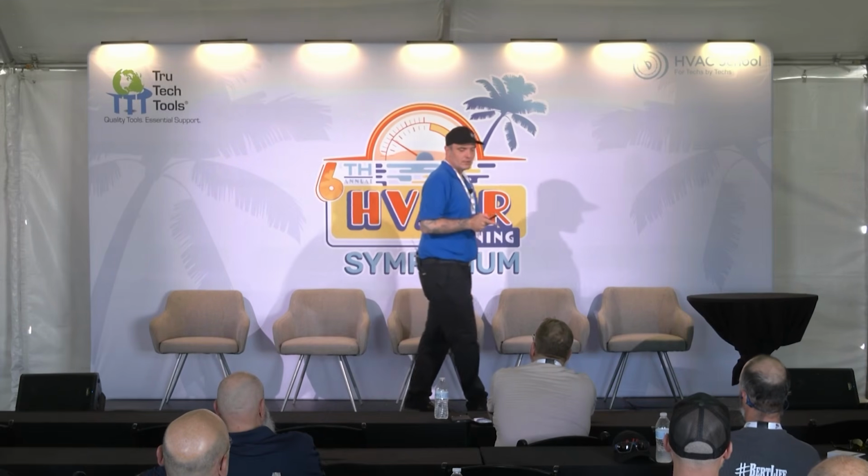One of the things I've noticed, and what I fell victim to when selling residential equipment, was that if you needed to replace equipment for somebody and you said, I need a 3-ton coil, I need a 60,000 or 80,000 BTU furnace, they would give you whatever coil they had off the shelf. So I would always try to pay attention to the rated pressure drop of that coil. You look at the AHRI matchups, right? You want to make sure you have a matched system, and you're also really paying attention to the pressure drop of the coil.